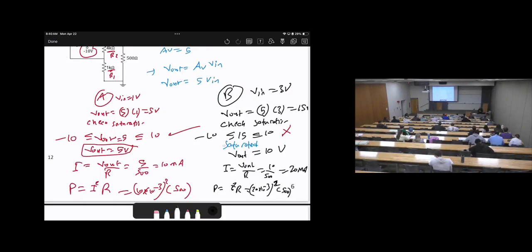So this is very important, especially when you have medical devices. If there's saturation, you can understand there's false information or some missing information. There's something wrong with the reading. Don't consider this reading. Okay? That's why we need to check saturation every time. Make sure, are we at the good level? Okay, does this make sense?